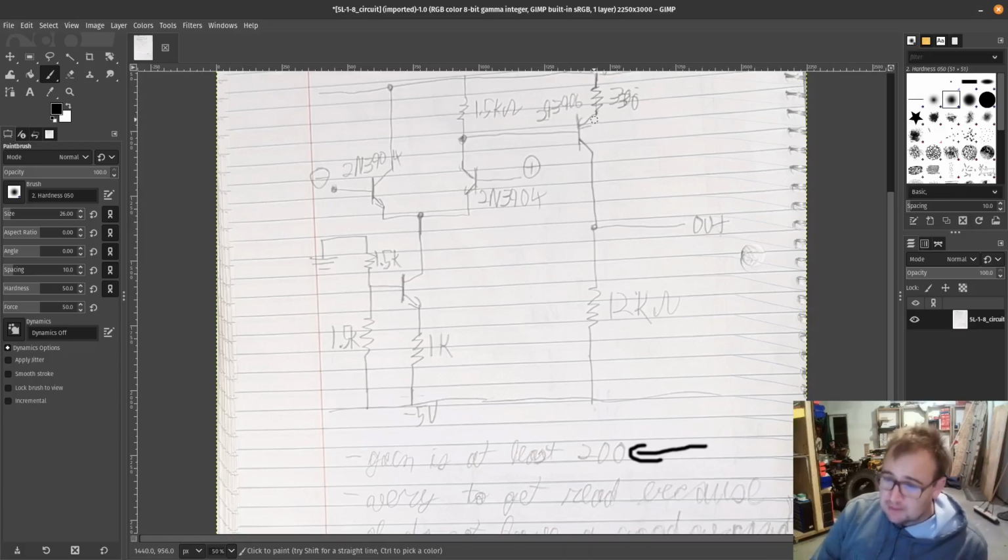Since I don't have that transistor array, I just use the 2N3906 transistor, and I have it right there. Then the 12K ohm is the same one that they have, and this is the current source. And then we measure the gain: watch input and output of the CE amplifier stage and measure this stage's gain. So let's go do that.